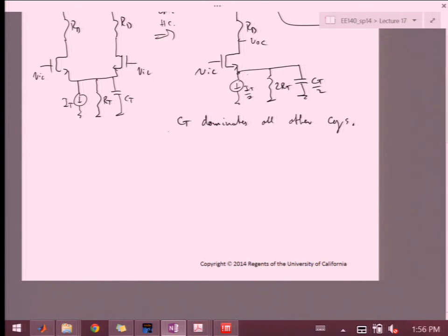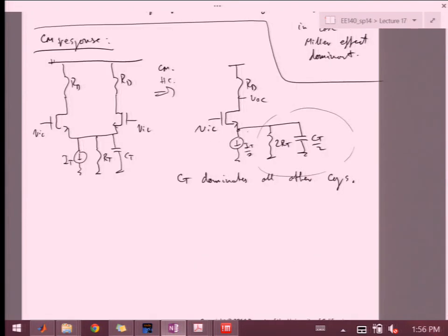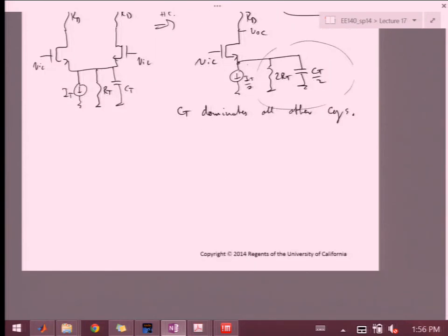So if this is the case, then I can treat this whole thing as just some impedance that loads my source-degenerated stage. And I can assume all other capacitances haven't actually kicked in, so 1 over omega C is pretty large on all the other capacitances. So I can still use my DC analysis, so to speak.